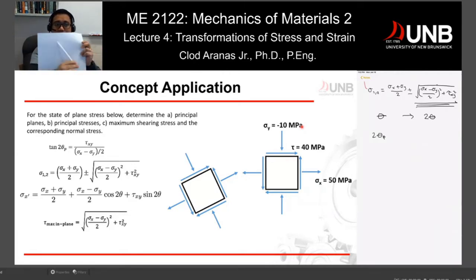There's a weld, for example, in this direction. You want to know how much pull, force or stress you are applying perpendicular to your weld, because that's the weakest spot when you are manufacturing a certain component. So that's the importance of determining the principal stresses or rotating to a certain angle.